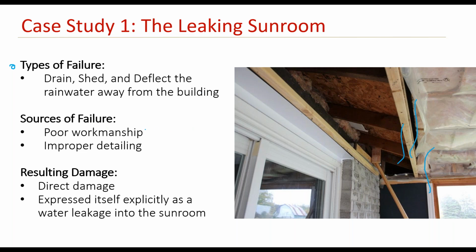We do have poor workmanship in terms of the framing, in terms of not removing the old shingles and just re-roofing and framing on top of the existing shingles. Also, poor workmanship was visible, or was obvious, with the improper chimney flashing.